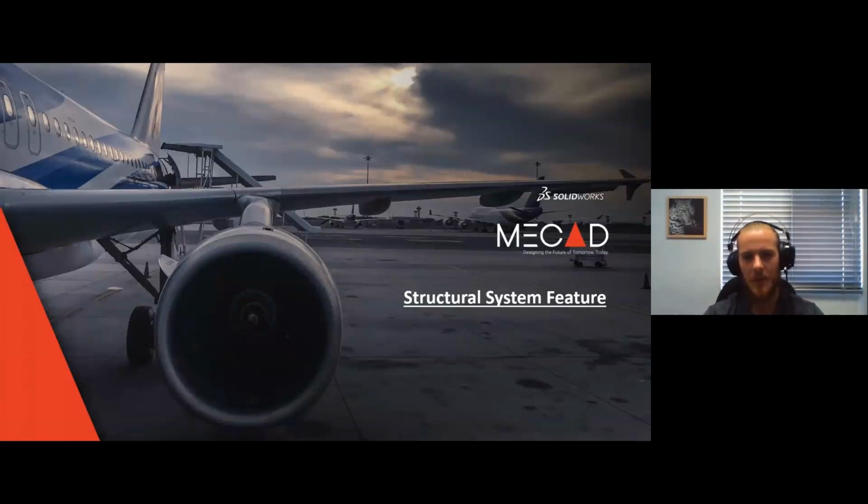So for this afternoon, guys, we'll basically be looking at two main categories. I'll start off by explaining the structural system feature, and this is specifically a feature that comes available when you look at the Weldments environment. It is not part of the Weldments tab. I'll bounce into the details as we go along. I just want to make you all aware that structural systems are basically a separate weldment environment apart from the Weldment tab that we all know quite well.